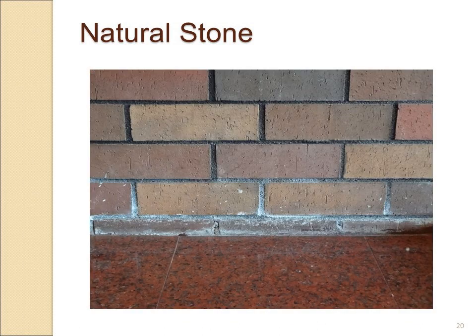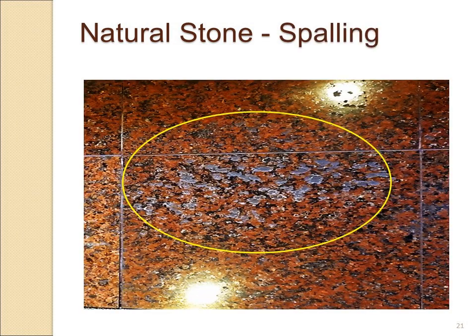When we consider that moisture is going to find its way up into a building, as we see here, we see the efflorescence forming on the brick. Well, what happened to the stone is it's spalled, and it spalled in all the areas where there was a high concentration of moisture. And this moisture is not evident when they installed it, otherwise they would have taken some action. But after they've installed it, it happened.